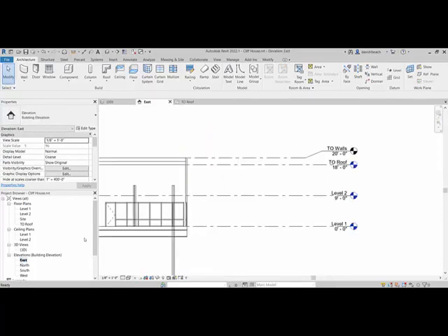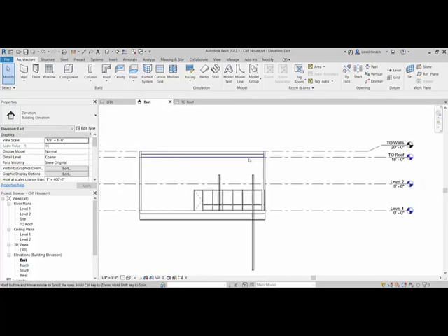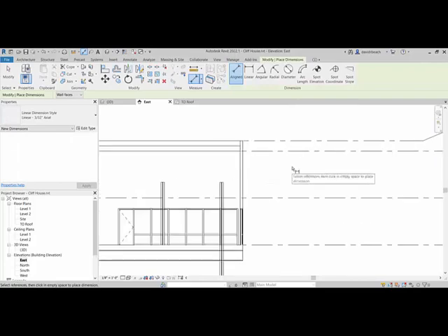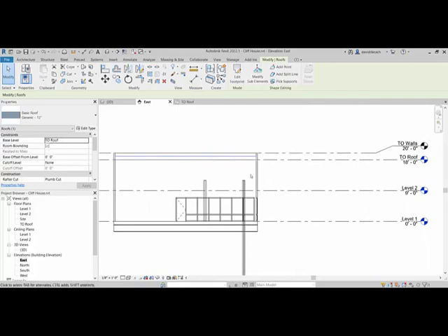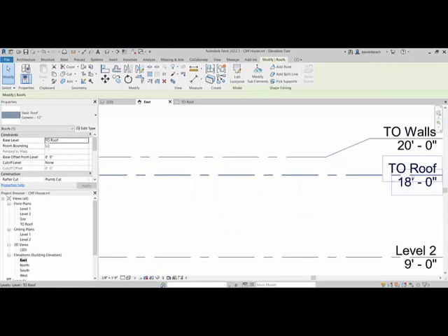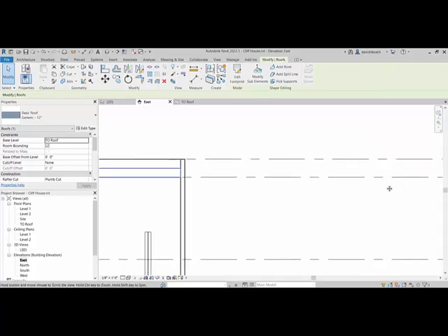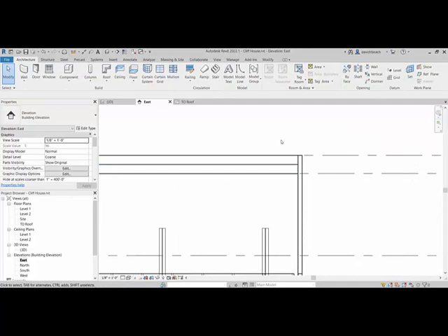So now when I look at that elevation that's in wireframe, you can see that is what I have right here. To do this really quick, that is a 9-foot gap. I am going to actually move that roof down by 1 foot. If you guys remember, floors project down, roofs project up. So I labeled this top of roof. And I want you to look at where my roof showed up. It built the roof bottom on the top of the roof mark. So the top of the roof is no longer the top of the roof, right?